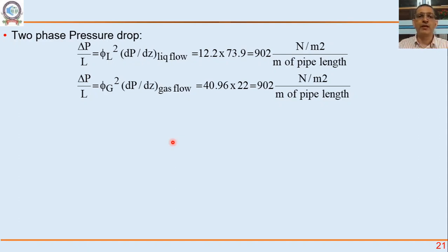Sometimes due to pressure, gas is generated. Say for example, if I'm trying to pump crude oil, let's say pressure where I'm pumping the crude oil is very large, so I have nice liquid crude oil going through. But as we go along the pipeline, pressure drops, so the gas solubility reduces, and the dissolved gas comes into the vapor state.